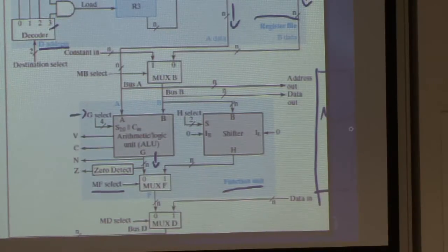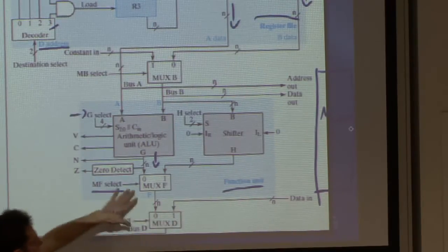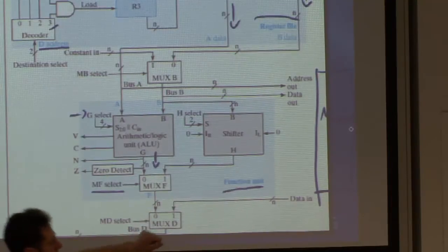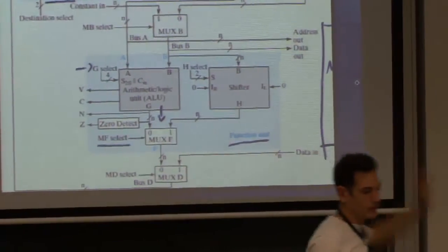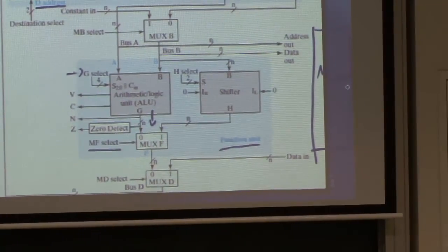So you might have a clock cycle where you don't utilize your function unit at all. It's there, it's a combinational circuit, it will be alive, but you ignore whatever comes out from it, and you just take a word from the memory, and when I say a word, I mean a value, and store it into one of our registers.